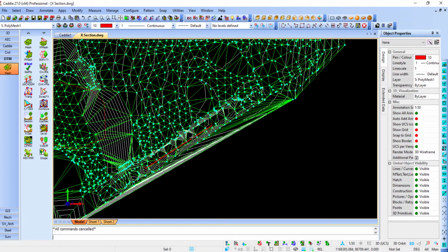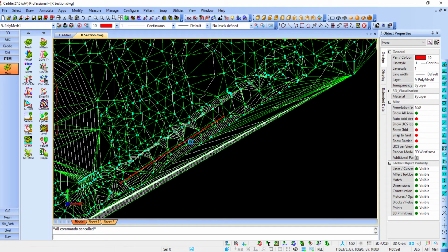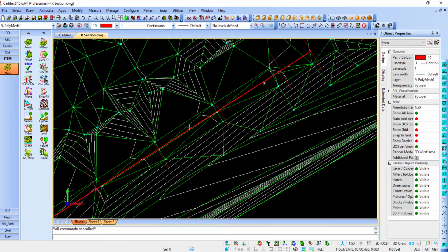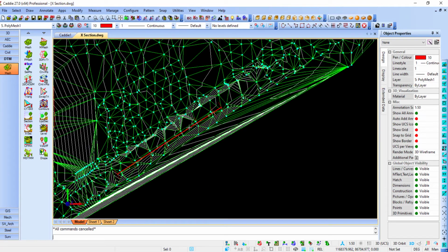As you now have accurate DTM data, you can then do cross sections as well, like on a piece of road. If you have a look at the bottom here, there's a polyline. It's actually physically running in the center of the road over here. You can then do cross sections by going to the cross sections command. It'll prompt you a couple of questions. First of all, it'll say, show me the polyline.